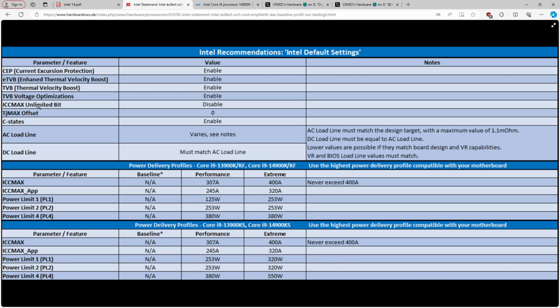And I would much rather have a CPU that runs between 1.45 volts and 1.2 volts with more overshoot than a CPU that runs between 1.55 volts and 1.2 volts, because the high load voltage isn't really limited by the load line settings, it's limited by the thermals, right? So if you have a cooling system that can cool 1.2 volts, it's going to be cooling 1.2 volts regardless of what your AC load line settings are, right?